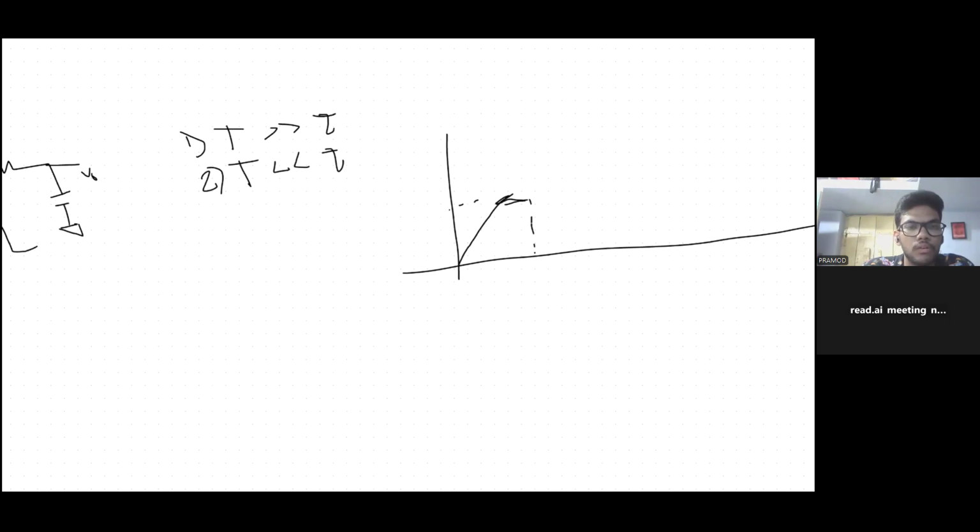Then at T by 2 plus, again the capacitor was short circuited, but it's holding the voltage of 5 volts, and there is a current which is flowing outside the capacitor. That means there is a discharging of the capacitor, like here. Yeah, it's fine. I think you got the correct way. I think you got the good concept here.